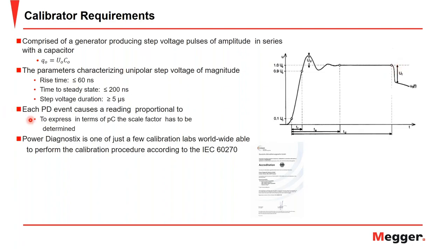And each of these PD events causes a reading proportional to the calibration that's taken place, to express in terms of picocoulombs that scale factor that is determined. And just a note, Power Diagnostics, which we recently acquired, is one of just a few calibration labs worldwide that is able to perform the calibration procedure according to the IEC 60270 standards.